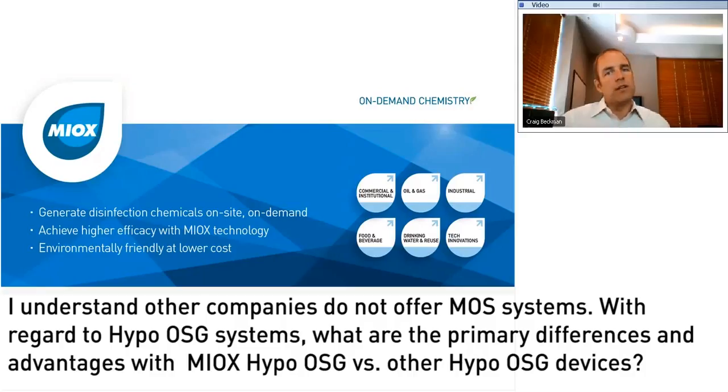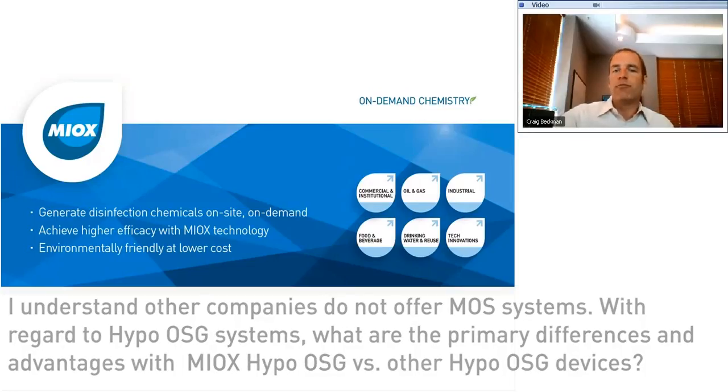If for some reason the chlorine is not doing the job, not controlling biofilm, not getting the log removal that they need, then we would recommend the mixed oxidant and recommend the customer pay the premium, both in capital cost and operating costs, because the electrical consumption is also higher in a mixed oxidant generator. So, hope that answers the question, but there is a distinct difference between the two.